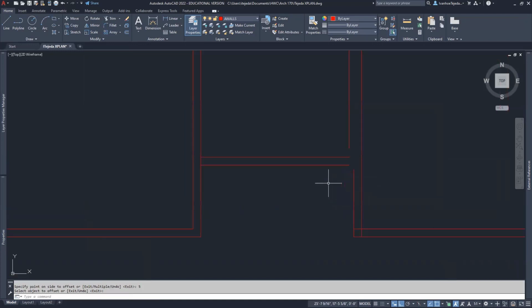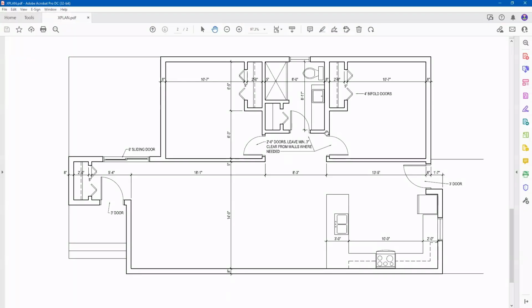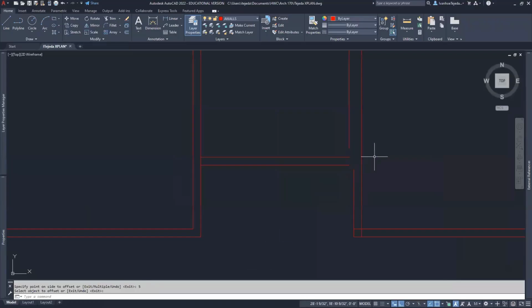And then from here, what I should do, let me double check the drawing. See, that's where it does transition. This is a 5-inch wall here. So I will go ahead and use the fillet command to finish that. So from here, I actually feel like using my fillet and the C option for crossing. So F, enter with the space bar, C, enter with the space bar.